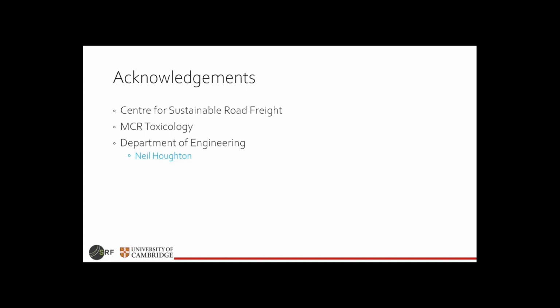Yeah. So the question is around how particles are being emitted and the process by which they're being emitted, whether it's friction, whether it's heat. The tyre components evaporate, so different components evaporate. But you are right, the friction events are creating a lot of really big particles, and that's well characterized. They looked at that, it was up to 400 microns of these particles coming off.